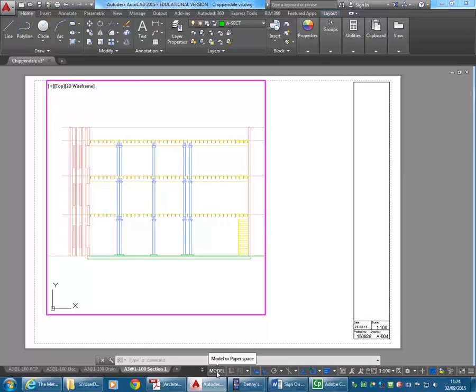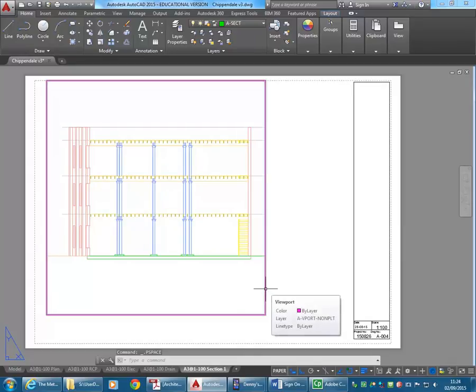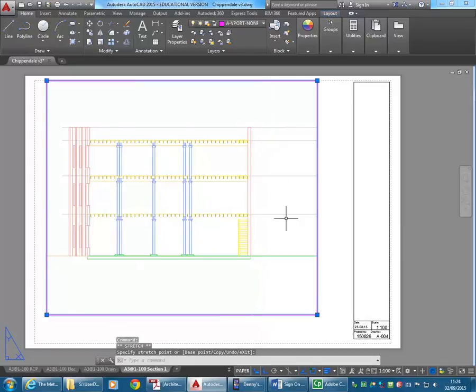Then clicking on the model button down the bottom, I might bring that down later more, but for now I just want to expand that viewport to the right so that I can see more, and I'll label those levels at some point. And so then I can do the setup for the next section, even though I haven't started drawing it yet. So I'm going to go back to the Model tab. And so again, notice I can't see all the tabs here, and that'll happen. So I just need to click on the double arrows when that happens, and you'll find all of them there.